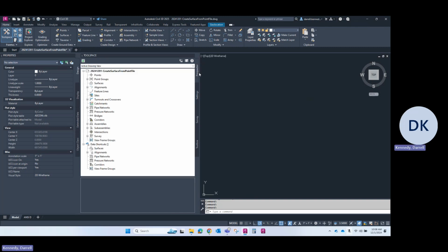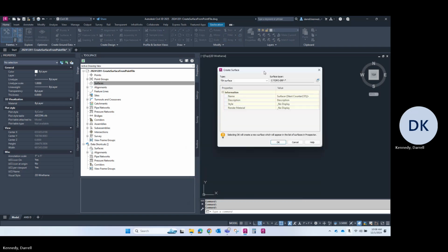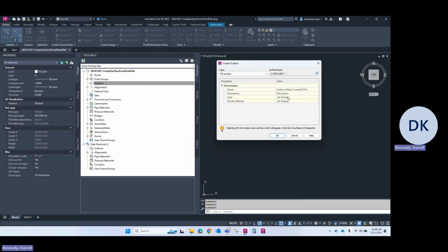So what you want to do is start by making a blank surface. Proper surface naming is always important as well. So we'll say V for survey. It's existing grade, so I'll use existing grade. It's a bathy surface, so I'll say bathy. Typically, I put the date that the bathymetry was collected, but not necessary in this scenario since it's an instructional video. And then we'll do all three spacing.